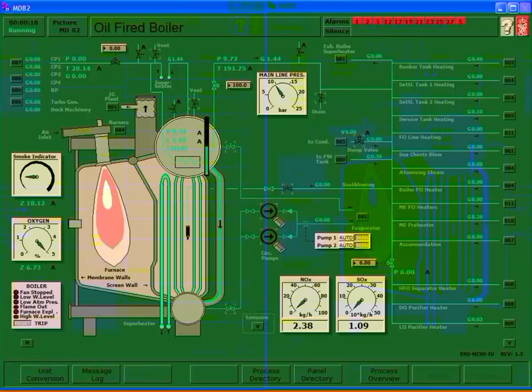But what can happen on your drains, for like your headers, or your blowdowns, there's a chance that those valves can leak, and when you draw a vacuum in the drum, that could pull unwanted water out of your bilge or from the sea into the boiler. So you get down to say 25 pounds or so, you want to open up the vent, or the air cock, so that steam is coming out and you don't have to worry about pulling a vacuum.